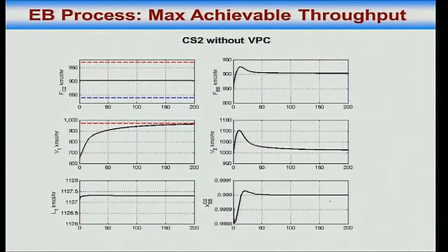How much? 13%. That's a big amount of difference. Okay, and it's all got to do with the control system that you've implemented. Yeah, same process, same everything. This control system accounts for what constraints are going to become active, right? That is able to get you to whatever was the maximum achievable. This control system will fail.